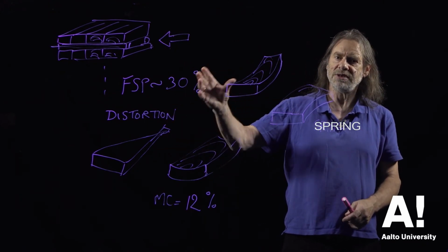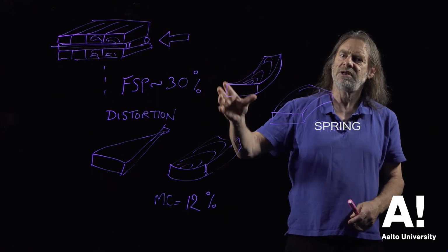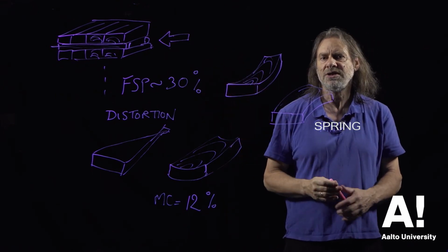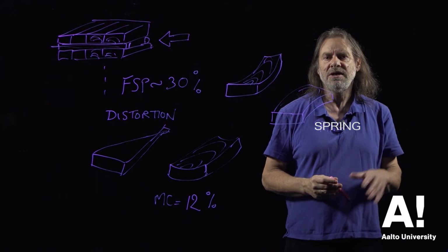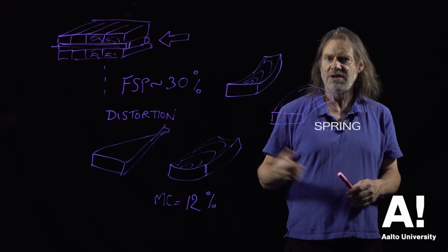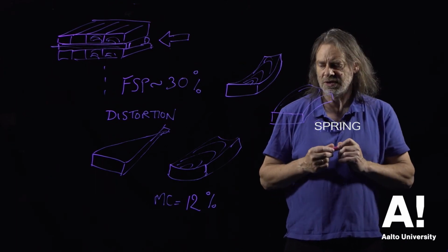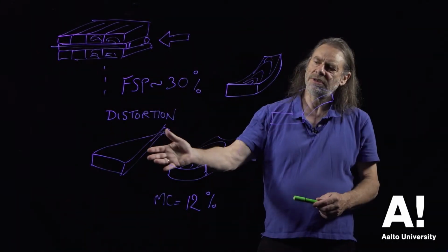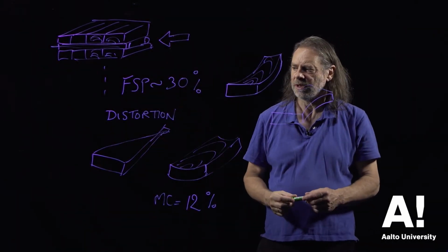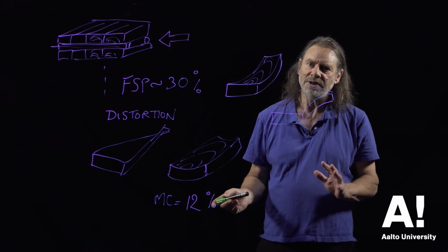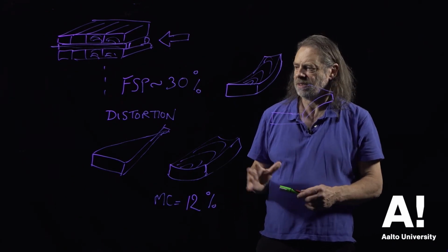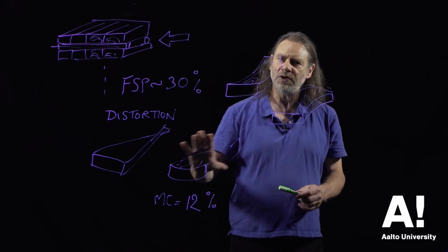And that's one of the reasons that at the end of the process we then have to go through a selection process where we have to decide where that wood can be used, or indeed whether that wood is acceptable for service or not. Okay, so these are the different types of distortion that you can get when you dry wood incorrectly. In some sense it's impossible to avoid some distortion.